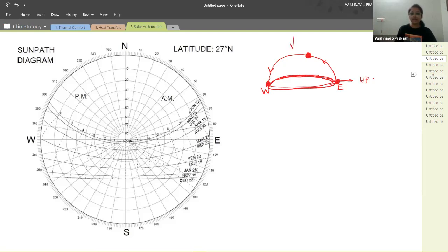And when you plot it on a 2D compass-like diagram, which is called the sun path diagram, you can determine the sun's relative position. So you can determine at what angle the observer is observing, or relative to north, at what degrees the sun is moving, right? Because the sun moves more towards the south during winters and is almost above our head during summers. In the southern hemisphere, it's the opposite. So let's take a look at all the different values and lines on the sun path diagram.